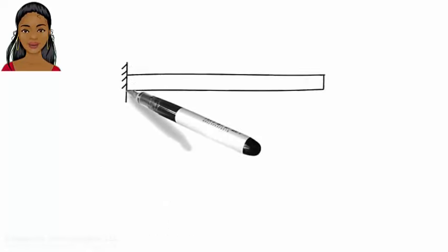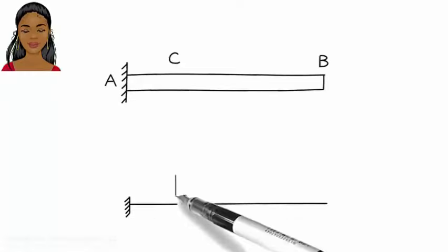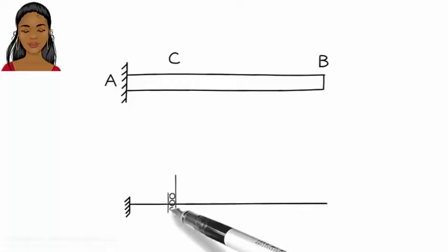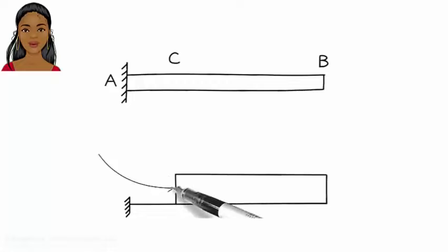Here is another example. Here is the shear influence line for point C. What is the height of the influence line? We know that the overall height at the vertical rollers is always 1. Since in this case there is only one height, on the positive side, then it must be 1.